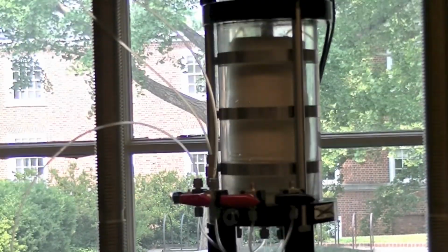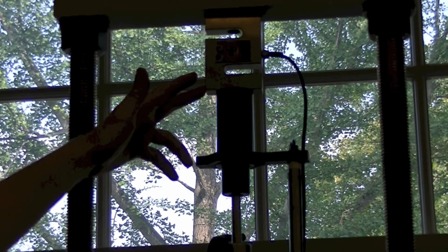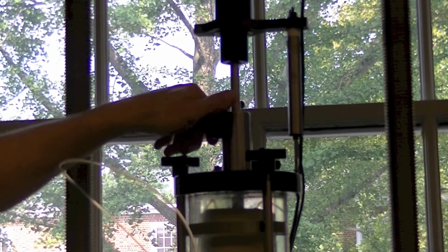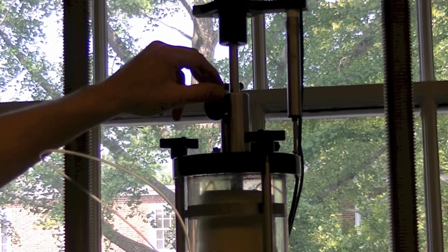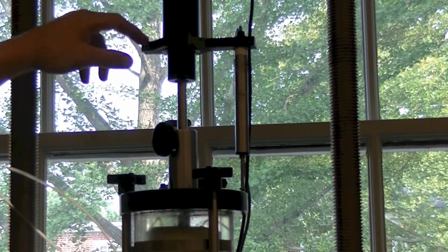Keeping the confining pressure on the specimen, move the triaxial permeameter to the load cell. Attach the bushing to the load transducer so the top platen is in series with the bushing. Position an LVDT so that it is capable of measuring upward movement by the master loader platen.